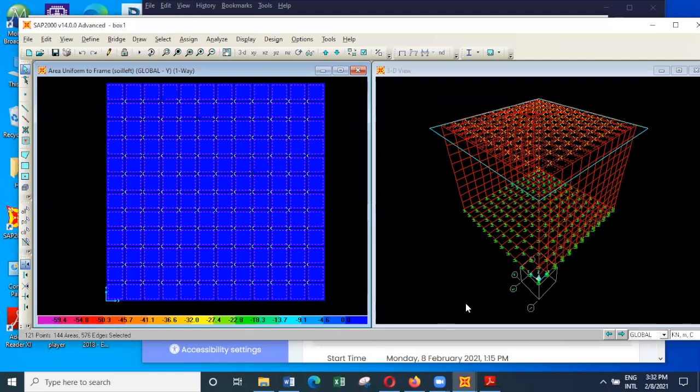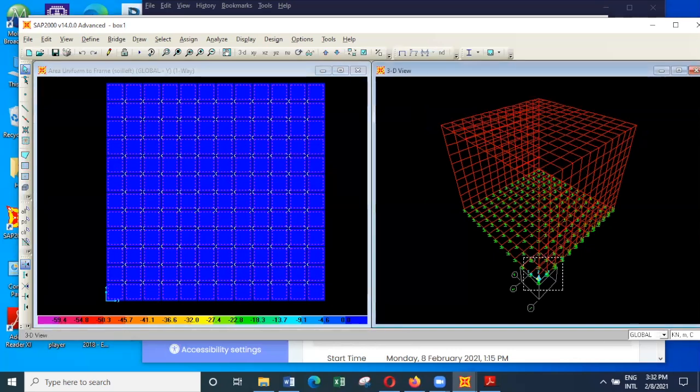So basically you will select one shell element and you can replicate it in all these directions and then replicate the whole thing in that direction. Then you can easily create a model like this. I'll not spend time creating a model like this because it's very simple. But the other important thing is, when you are doing the analysis, you might need some special arrangement.